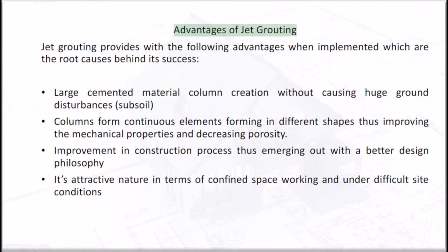Advantages of jet grouting. Jet grouting provides the following advantages when implemented, which are the root causes behind its success. Large cemented material column creation without causing huge ground disturbances in the subsoil.